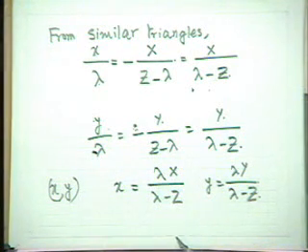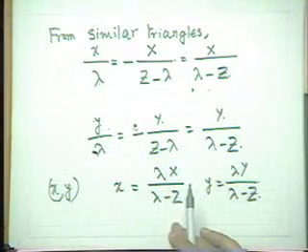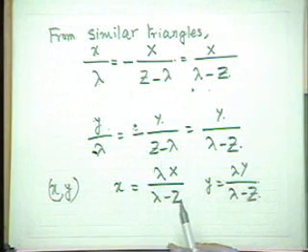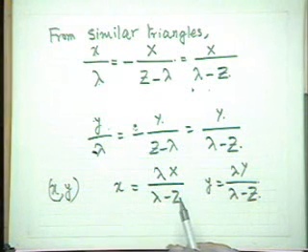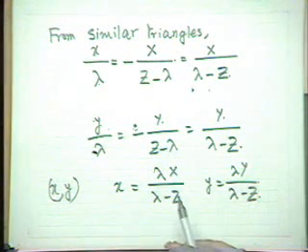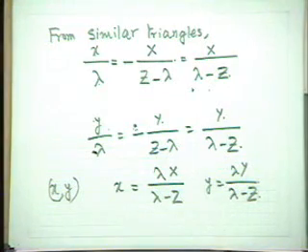But actually speaking, what we should try to do is to represent this world coordinate as well as the image coordinates in terms of that 4 by 1 column vector which we were doing the last time, so that we can also define the elements of the 4 by 4 transformation matrix.